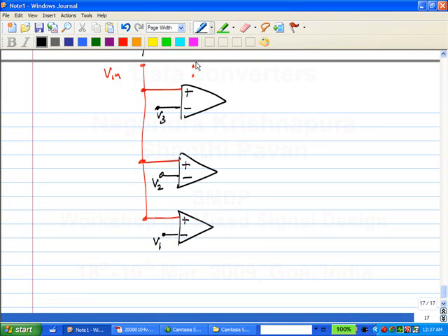Correct? And at every point, what you're supposed to do is the NOT of the comparator on top ANDed with the decision of the comparator below, and so on.